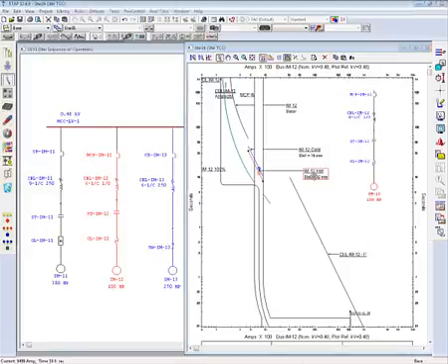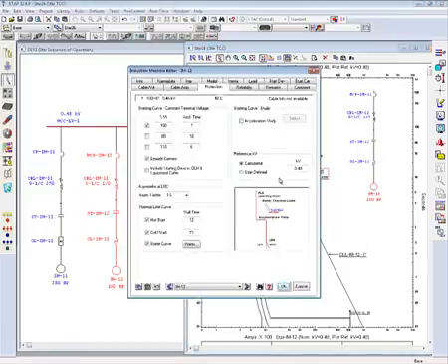You can double click on any of these elements and open the associated editor, where you can see all of these settings. So I have thermal limit curve settings for hot start stall point or cold start stall point, and stator damage curve.